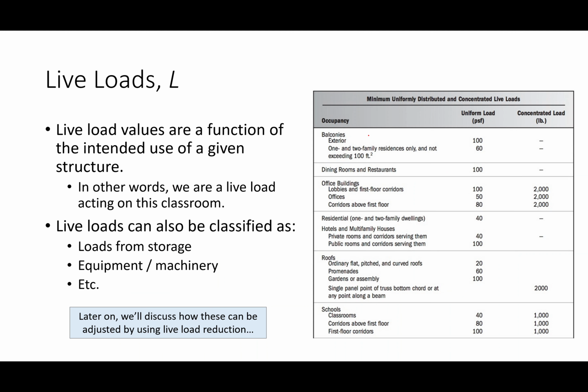What about live loads? There is a word that you will hear me use with live loads pretty commonly. Sometimes I will use the term occupancy. Live loads are what the structure's being used for. As you mentioned, in classrooms you suggested a live load of 50 pounds per square foot. We actually see 40 specified here, but you weren't that far off. So the live load in a classroom is typically taken to be 40 pounds per square foot.